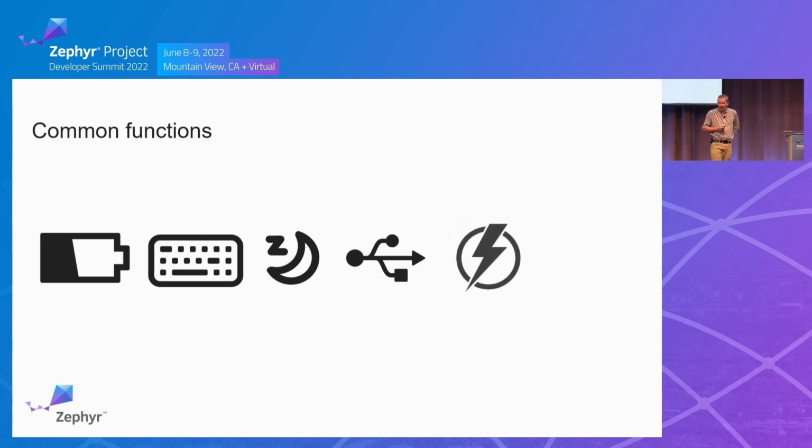And speaking of power, some APs need a particular sequence to be followed when powering up, with each voltage rail enabled in turn with suitable delays. The EC handles that too. There are also sensors connected to the EC to detect the lid angle, system temperature, and so on. There may even be an accelerometer, gyrometer, or a compass. These must be tracked so the EC knows the orientation of a convertible laptop and can deal with things like getting too warm by turning on the fan or telling the AP to slow down.